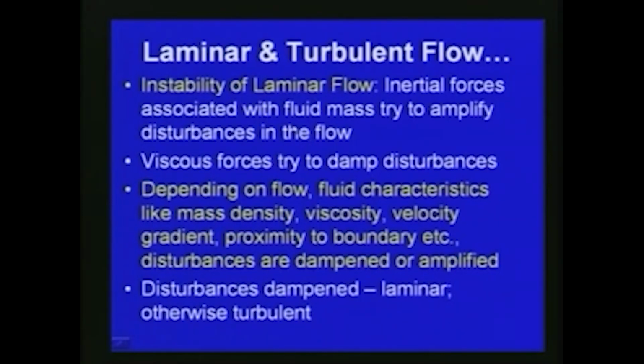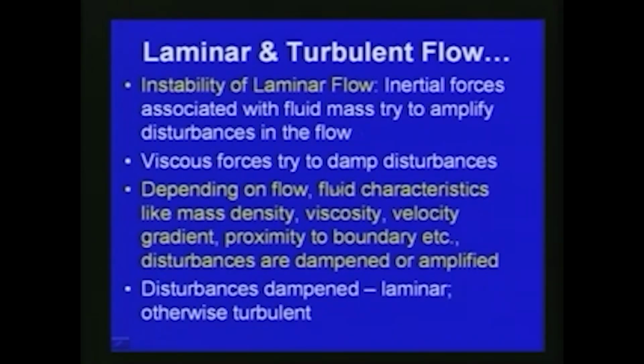Initially the flow is laminar, but there can be different kinds of disturbances like boundary friction or shearing effects. The inertial forces associated with the fluid mass try to amplify the disturbance in the flow. Then we say that there is instability of laminar flow.